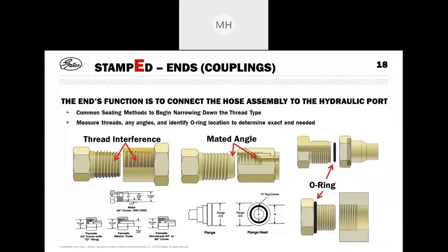They have different thicknesses of the flange, but they all work on the same principle, that they have a flange face with a recessed groove machined in for the O-ring to be seated in there. And then they have clamps which go over the outside to hold the flange firmly against the face of the port and the block or the valve, depending on what the application is.